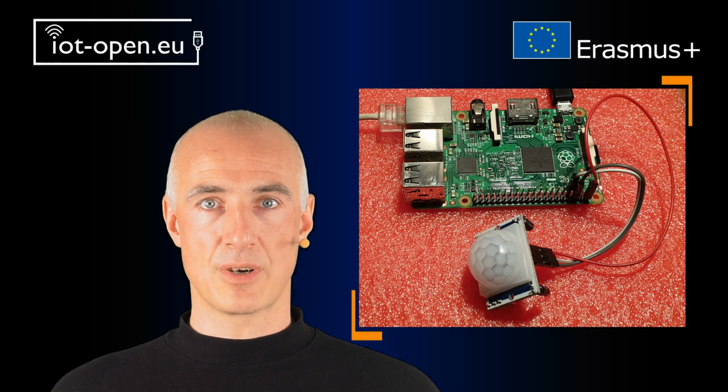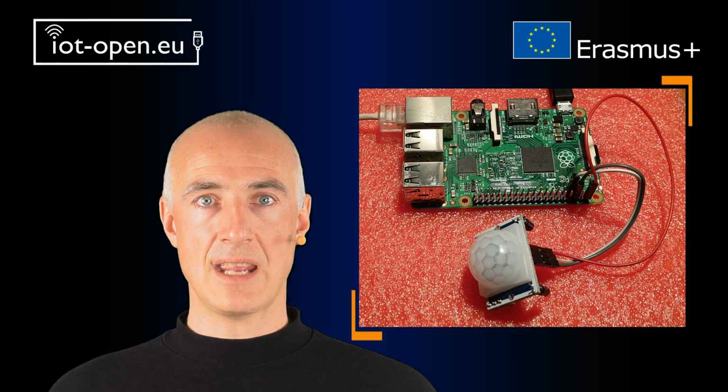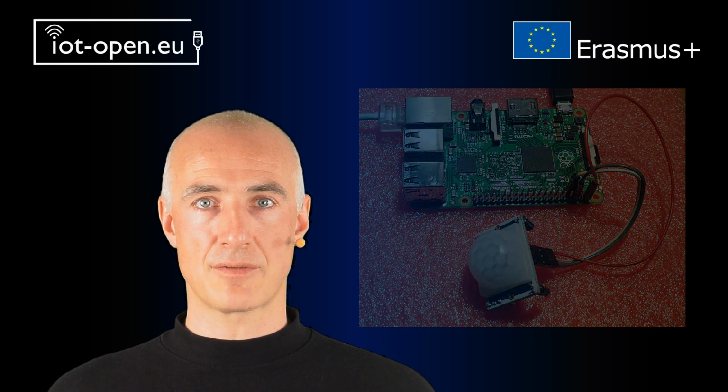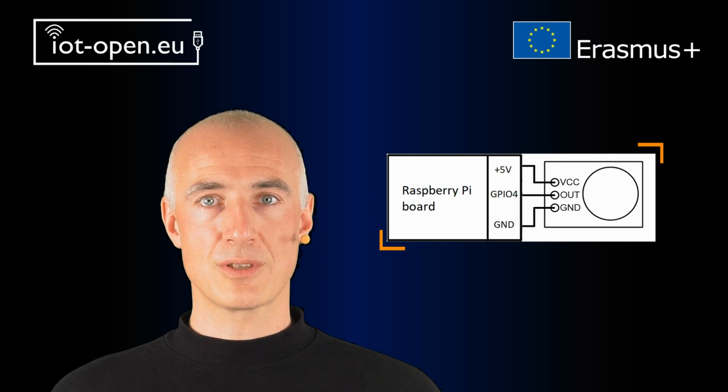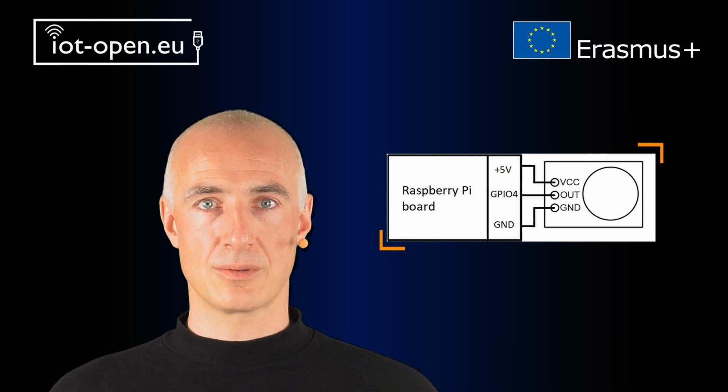Motion sensors are usually used for security purposes, and in automated light and door systems. As an example, in IoT, the PIR motion sensor can be used to detect motion in security systems of a house or any building. The laboratory testbed for the Raspberry Pi board uses the HC-SR501 infrared motion detection sensor. As previously, we use GPIO4 to connect the sensor to the RPI board.